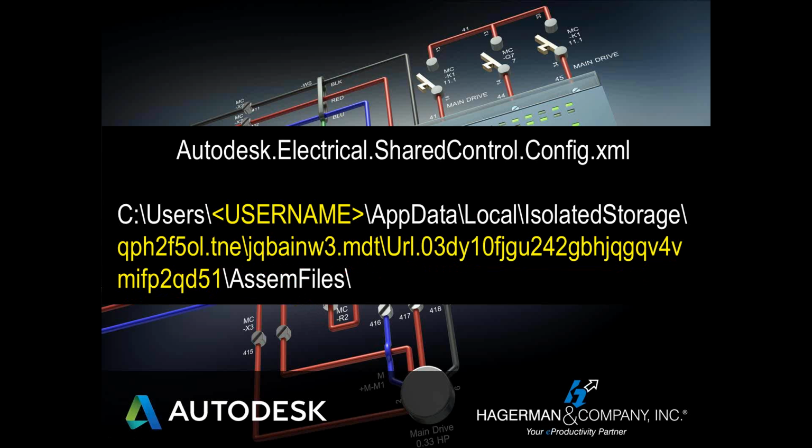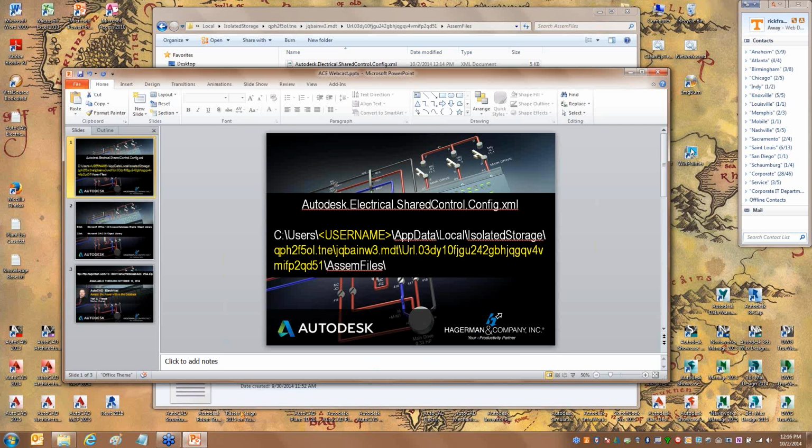Now, another method is if you ever want to just clean it up, that list has gotten too unmanageable, you can always just delete this file, open AutoCAD Electrical, close it, and it will recreate this file, and it'll be cleaned up with nothing in it. But if you do that, be aware that you'll lose your favorites.